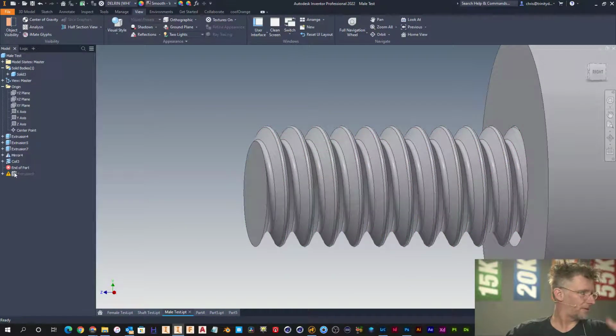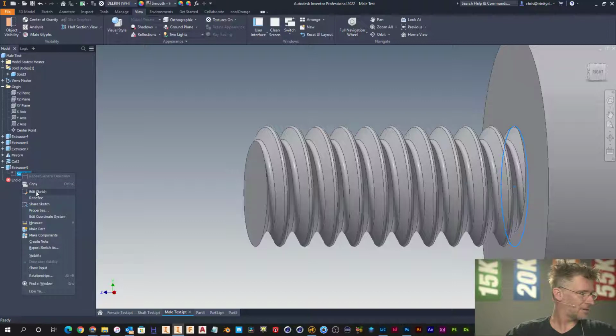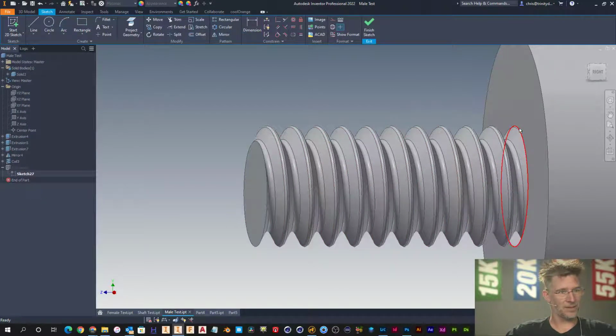We're getting it solved. Now what we want to do here on this bottom part, to ensure that when we change that it gets covered up, is we're going to want to figure out a way, instead of projecting that surface, because that surface is arbitrary, to find the center of the circle right there, and we're going to draw this circle to be nominal OD.